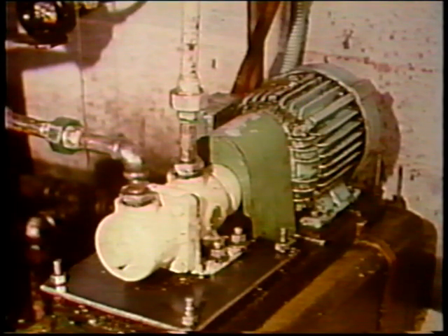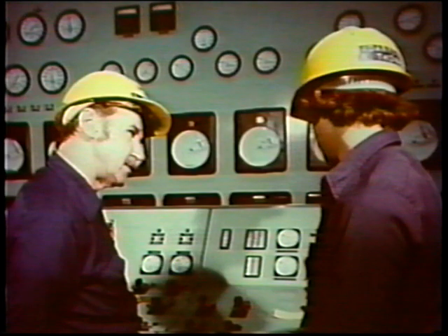Now, let's take a look at an example of how to use these 6 basic steps of troubleshooting. Remember now, the 6 basic steps of troubleshooting are know, question, evaluate, inspect, repair, and test. The electrician has been assigned to troubleshoot a lube oil sump pump. The first step in troubleshooting is to know how the pump normally operates. In this case, the electrician asks the operator to describe the normal operation of the sump pump.